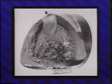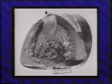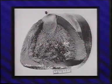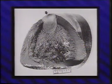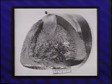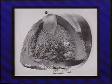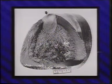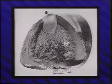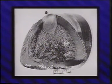The shaft became so weakened by this large stress concentration that only one additional torsional load application was necessary to cause the final rupture. The well-defined chevron marks in the relatively hard, brittle induction-hardened zone around the surface point toward the fatigue fracture origin. Inside the shaft, the considerably softer core shows a rough surface, characteristic of a rough tensile fracture in a ductile metal. This fracture is at a 45-degree angle to the shaft axis, typical of the fatigue and brittle fractures of shafts